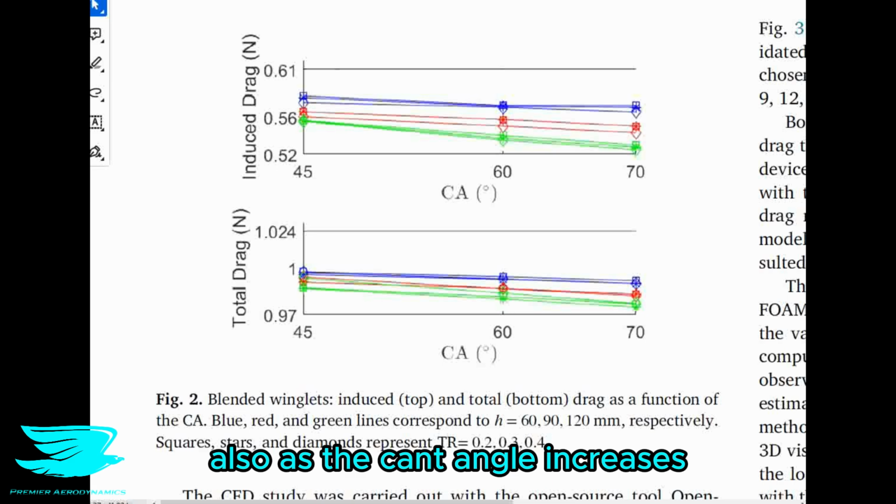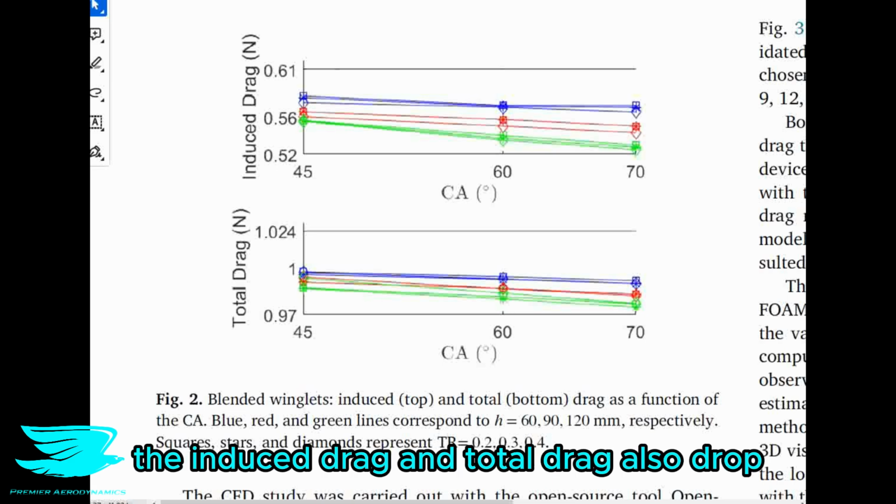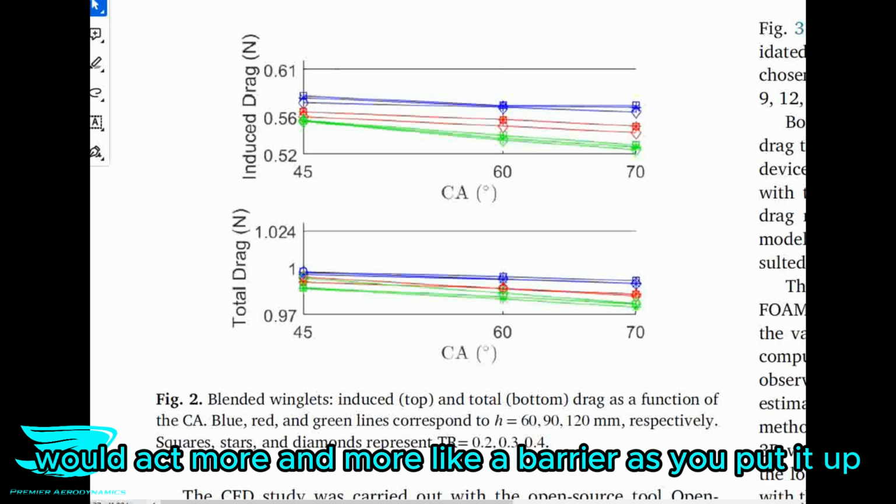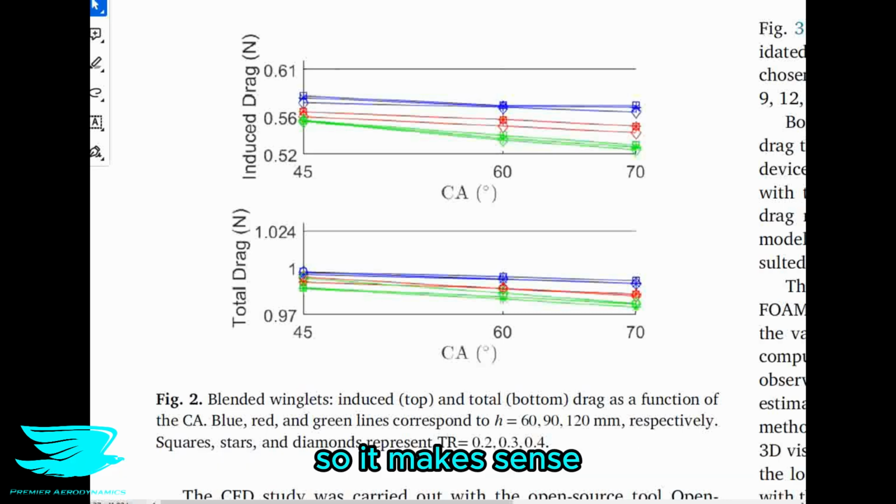Also, as the cant angle increases, the induced drag and total drag also drop, which also makes sense because the winglet would act more and more like a barrier as you put it up. So that all makes sense.